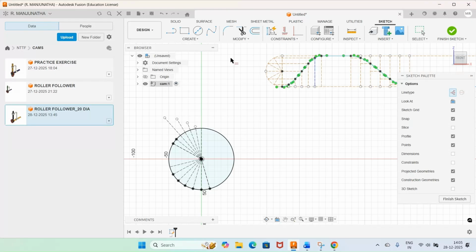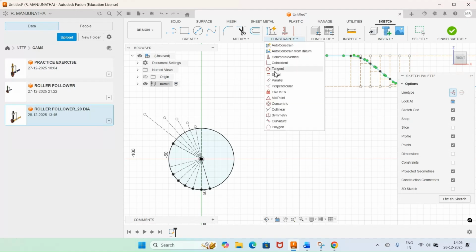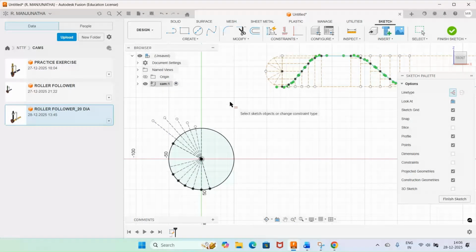That is this one. So again go to line, select some arbitrary point and then draw this line. Again go to coincident, select this line and this line. Okay. Then again go to collinear, between this line and this line. Now we have this. So which is the next point? I want to take this point, go to constraint, equal. You select this line with reference to this. Okay.